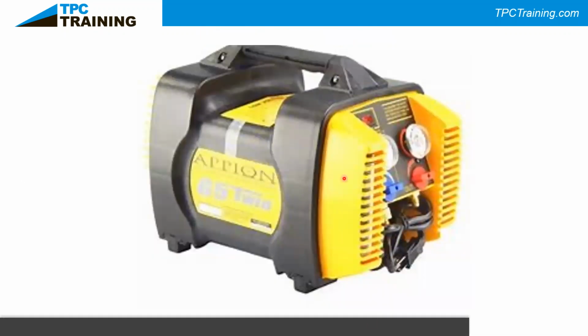This is another picture of a recovery machine, some of the different recovery machines we see. This is a new style recovery machine. The older style recovery machines that I started out with could not recover liquid, so it made the process longer. I had to recover only as a vapor, and it takes a while to get all the vapor out. Where with liquid, I can do it faster. These machines now will tolerate liquid as I'm pulling it off and allow me to do a recovery faster.